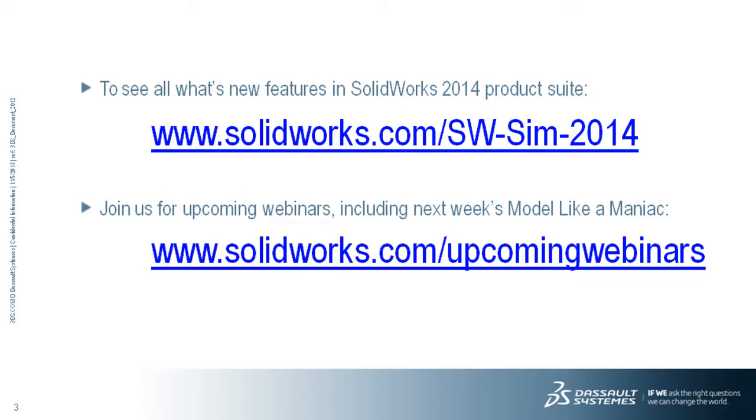But if you have not defined your Toolbox fastener in SolidWorks, that's all right. You can define in SolidWorks Simulation the bolted connector with the material data, with the strength, with the preload. So going through the mapping from Toolbox to connector is not mandatory. It's just a solution when you have done that work already.